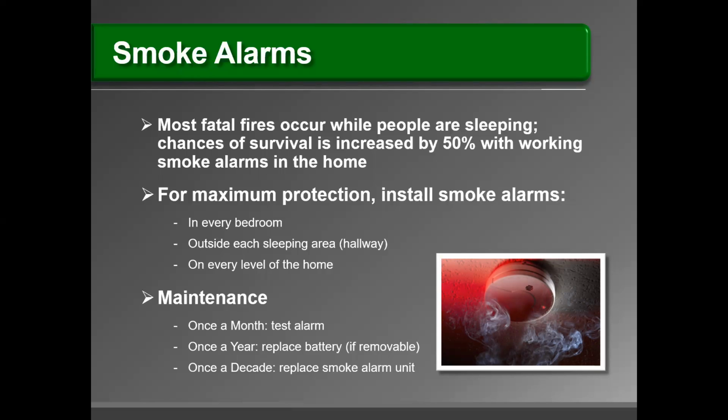You should be testing your smoke alarm once a month, and if you look at the smoke alarm, there's a test button. If you can't reach it, you can use a broom or something, and you should test that. And the shelf life on smoke alarms is about 10 years. So I recommend when you install new ones to take a Sharpie pen, and on the bottom side, before you attach it to the ceiling, put the month and the year, so that if it starts to go bad, you can tell how long you've had it up.